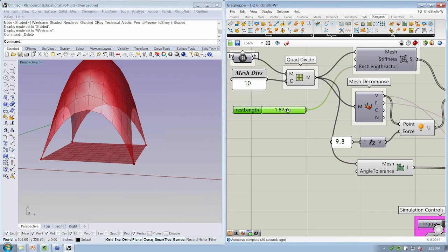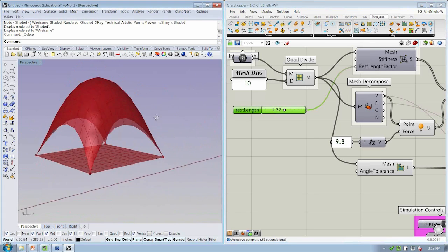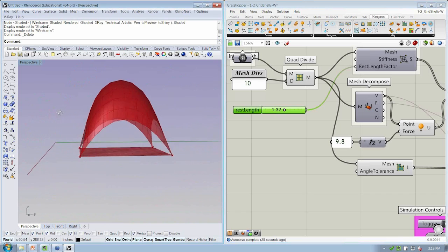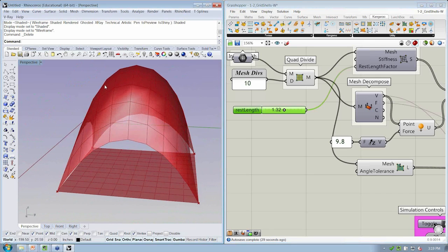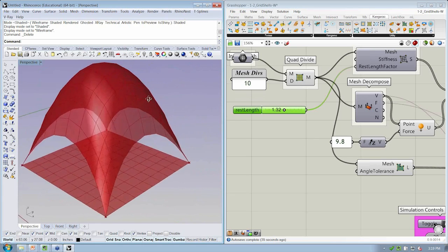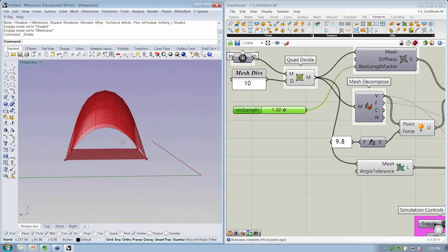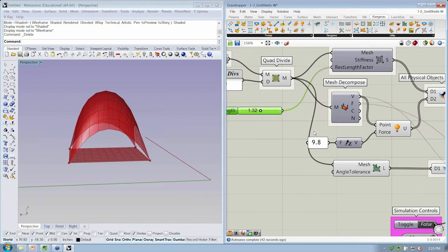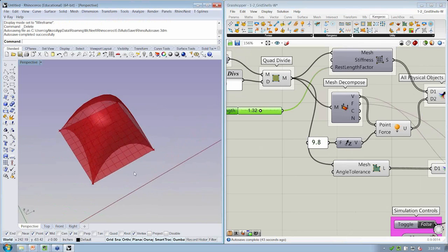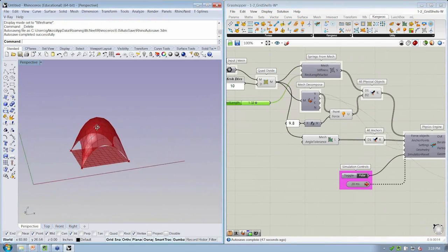So if we're about 1, now instead of being in a completely tensioned system, right, we have a grid shell. Our curvature is convex. If you're looking at it from the inside, convex in both directions, right, as you move through the grid shell. And it's very much influenced by the pressure of the gravity force. All right. So this file seems to work, right?